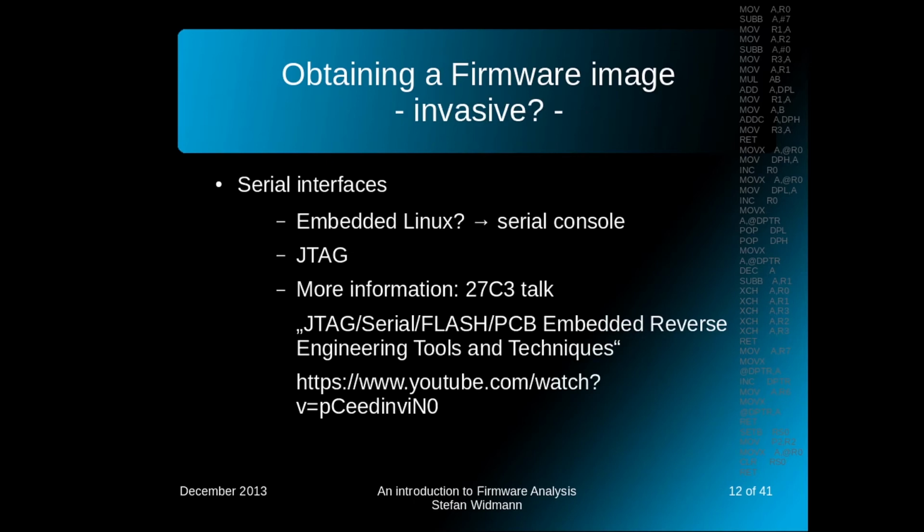We'll search for serial interfaces. Sometimes they are accessible without opening the device, sometimes not. Do we have an embedded Linux system? Yeah, we search for serial console. Maybe we have to use JTAG. There was a very good talk on 2073 about JTAG, serial, flash, and so on. So I've included a link here.